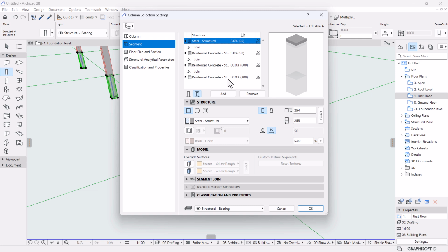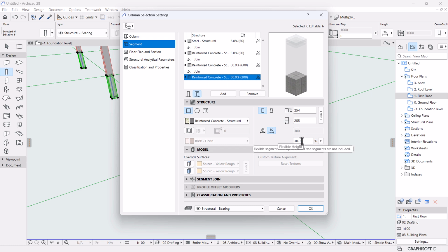So like I said, the materials are also critical. The first one is the top plate, and then all this is concrete. Now we need to set up the widths of the elements. Instead of setting it here, which I wrongly did before, and that's why I ended up messing up the entire structure, you need to set up the widths here. So I'm going to link the dimensions first, then set the footing to be 1 meter wide, or 1000 millimeters wide. You can see on your preview, this is basically what we try to achieve.